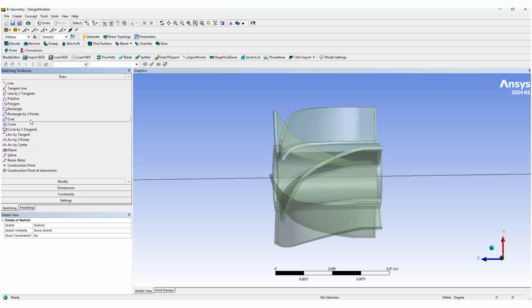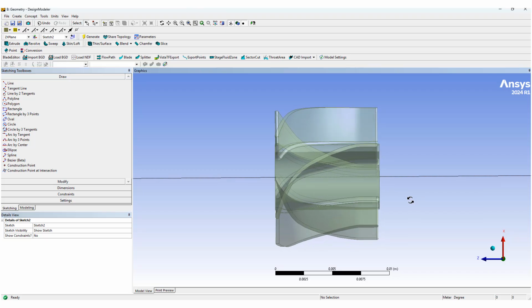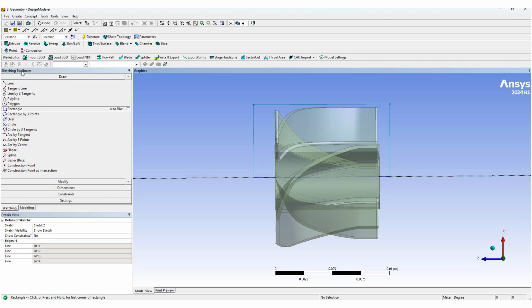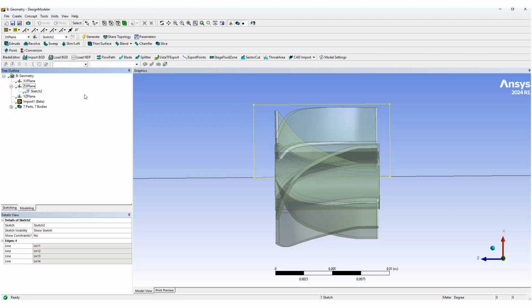If you go to the sketching section, we have a lot of alternatives to use. We'll use the rectangle, and let's make this aligned better. So I'm gonna select the rectangle and then provide some cushion, if you will, on the front and the rear end, and use only the upper half of the body, and the rectangle is gonna end by the axis, as you see here, and that is it. We have our sketch available.